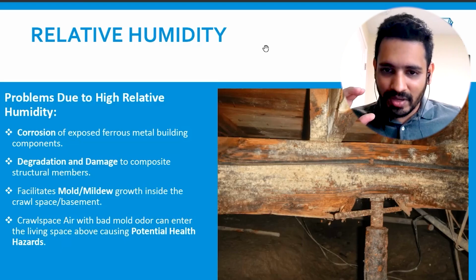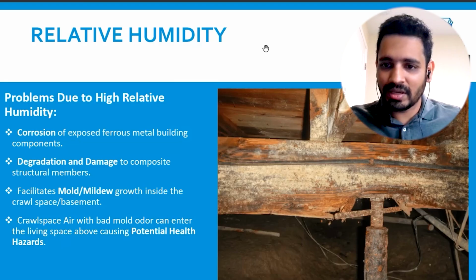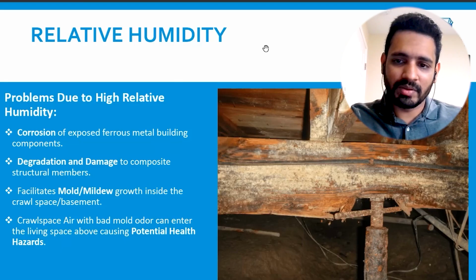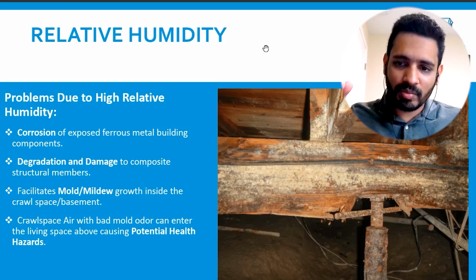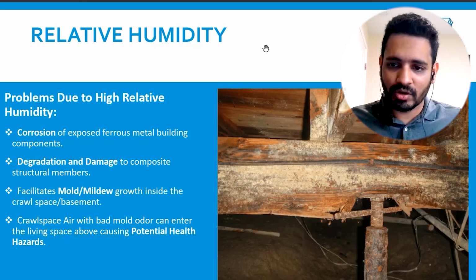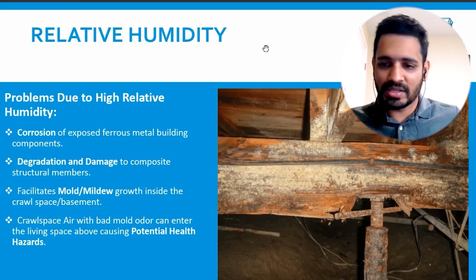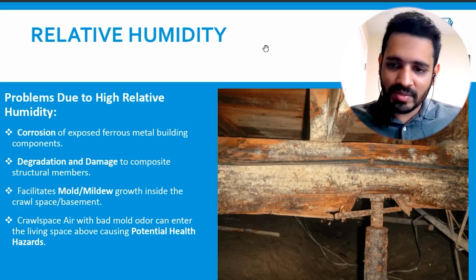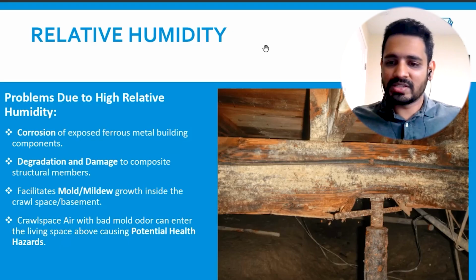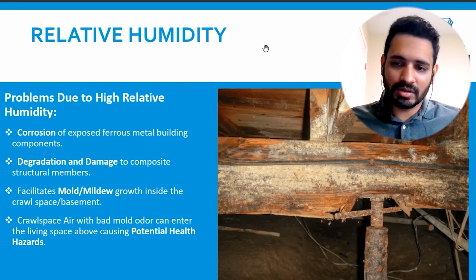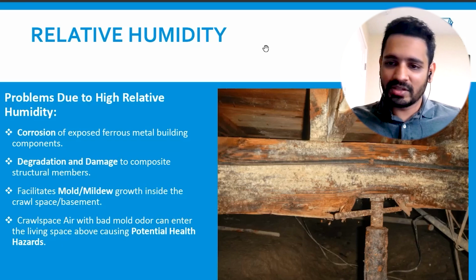It is not a built-up section. We're not looking at a top section and a bottom section above and below the cable. It is a single 4x6 beam that supports the floor at every 4 to 5 feet spacing. The beam is supported continuously at regular spacing by these metal screw jacks, or metal jacks that can be adjusted.